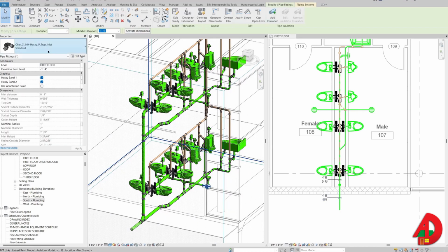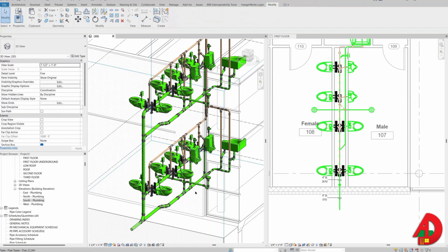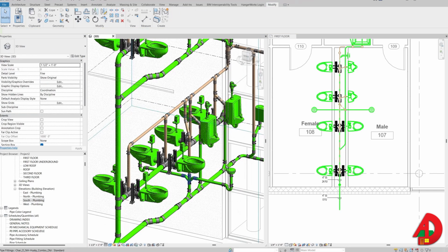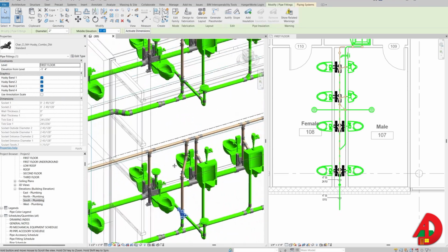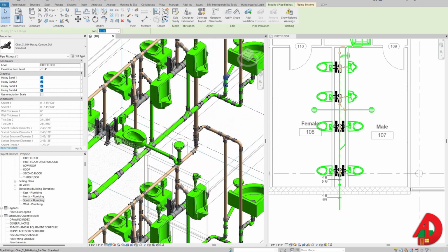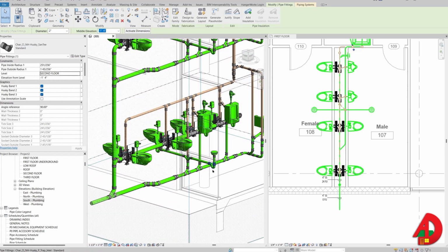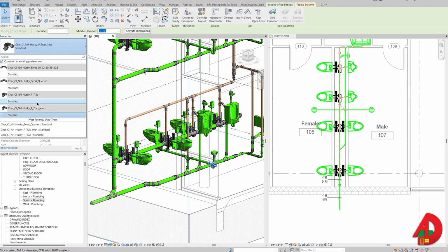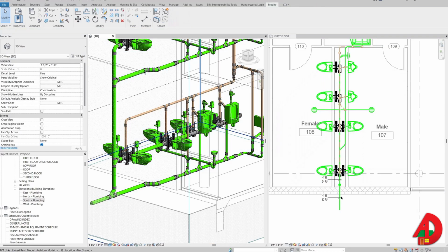I found that if I replace this inlet P-trap with a regular P-trap, we'll fix this problem. It seems that this happens because here I have a cross fitting that has 3 sanitary connections and one that is a vent. Or sometimes the sanitary T, for example, has 2 sanitary connections and one vent. But it turns out that if I swap a fitting close to these points that create a disturbance in the system, I can eventually force it to calculate total fixture units.